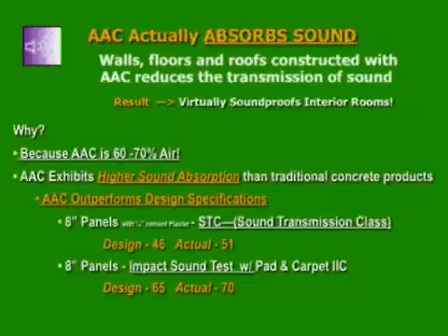So as an example here, you have an 8-inch exterior wall and a car alarm starts outside, which creates around 110 decibel. Our 8-inch wall reduces the sound by 51 decibel, which is almost half. Calculation data based on the weight per area was calculated to resist only up to 46 decibel. Here we clearly outperformed it. Let's see the last test.